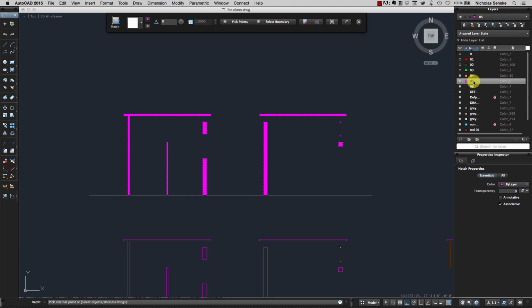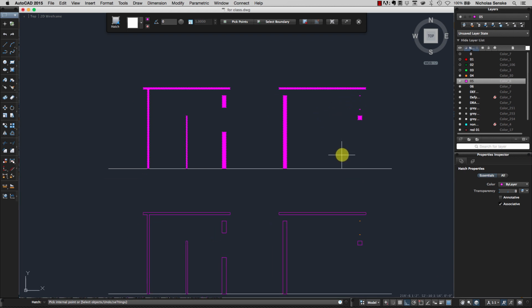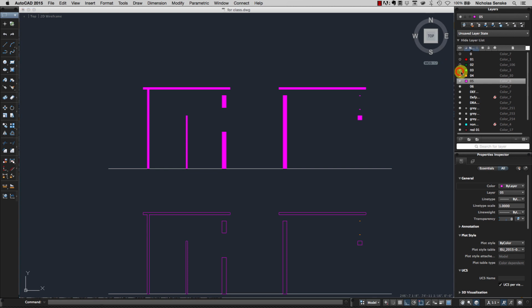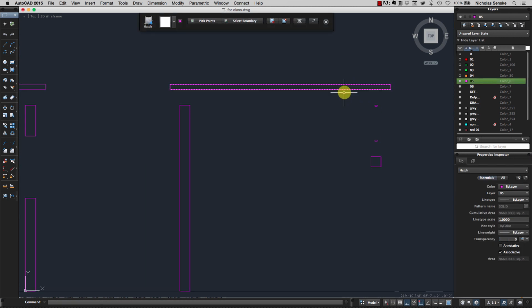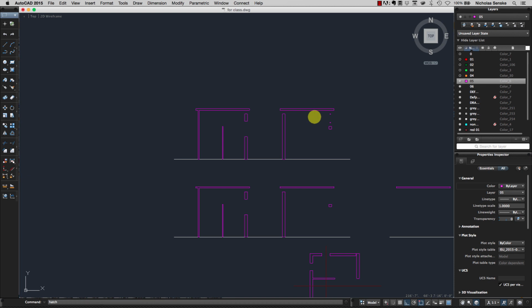This is a pretty dark weight, which will be more important later. But right now, solid is just black. It's going to fill it in. The weight doesn't even matter, because it's just going to fill it in. Okay, and if you press enter, that's your poche. That's fine. Let's try a variation of this. Let's delete this. Okay, go back to hatch again.